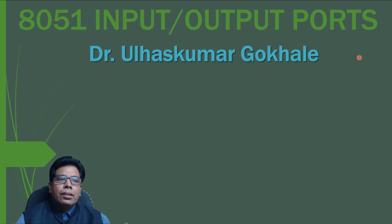Hello friends, the topic for today is 8051 input output ports or IO ports. A port is a pin where data can be transferred between 8051 and an external device. 8051 has four 8-bit ports P0, P1, P2 and P3. Apart from being used for input and output functions, some of these pins have other functions assigned to them as well. In today's video, we'll learn the input and output ports of 8051. Let us start.